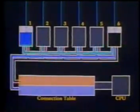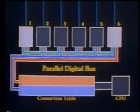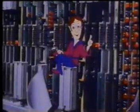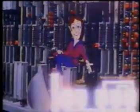However, in normal time, analog signals from both extensions will be sampled, coded, switched, and decoded 12,000 times a second, allowing multiple paths of digital data to be carried on the parallel digital bus. These are the basic principles of time division multiplexing and pulse code modulation as applied to the ROLM system.